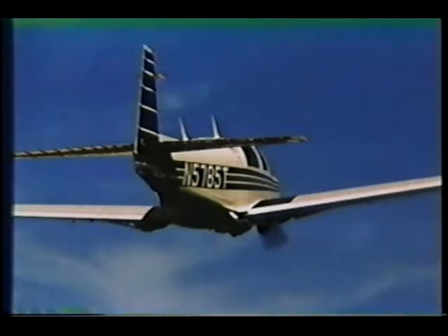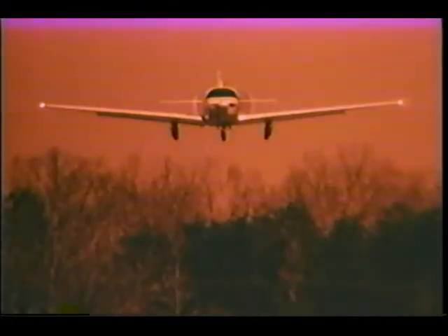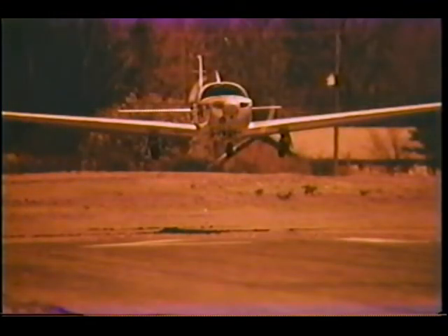What we're doing here is setting you up on final approach while you're still at max landing weight. Now we're going to ask you to come in over the fence at 1.3 VSO at max landing weight, okay? As we explained a few minutes ago, you have to complete the transition from the approach attitude to the landing attitude. Everything is going by the book. The approach looks great, and your touchdown's right where you intended it to be. No overshoot, no white knuckles, no sweat.